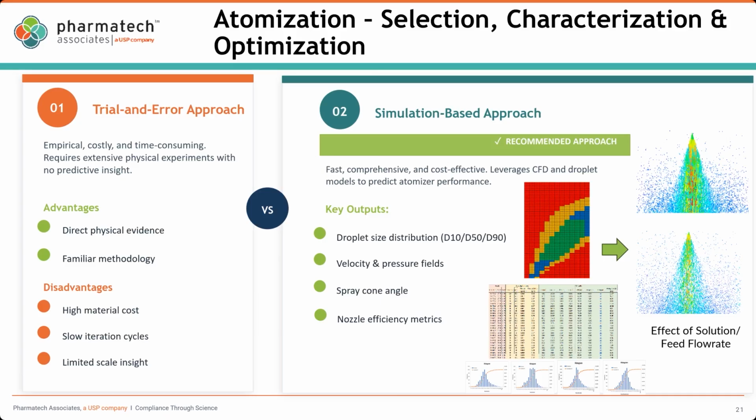Now we are running at PSD4, PSD3, which is huge. They need a lot of material. And when we come from the clinical trial or the pilot test case, there's not much material available even to do any of these things. So we start by developing a model, using computational fluid dynamics to simulate the droplet generation, the evaporation, the droplets that hit each other, and the coalescence or internal flow inside the chamber.